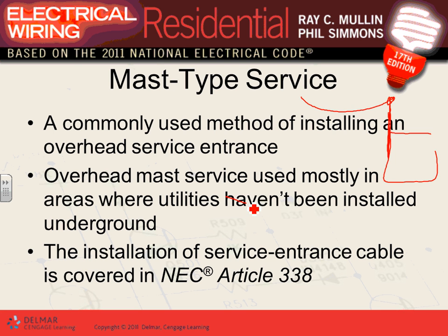You can also come from underground. I will remind you guys of the same thing: you can come from underground. Why do they come from overhead? Cheaper. Utilities come from overhead with service conductors, or service entrance conductors, or service drop, or typically service lateral.